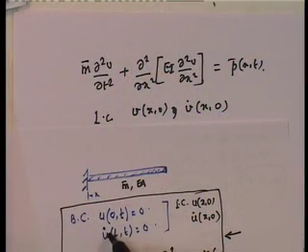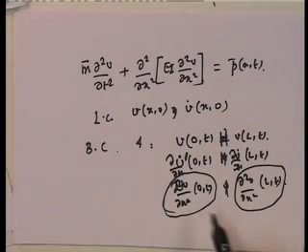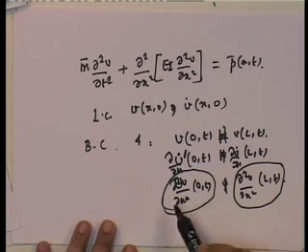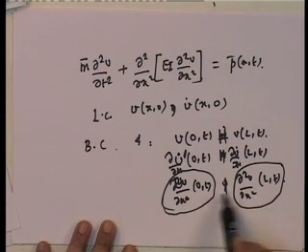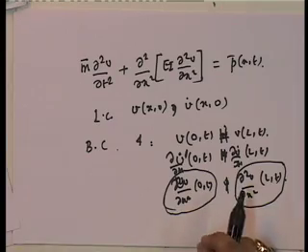Why is this? Because this is not strain, it is really the load, and there is no load here. So, the strain is equal to 0. Similarly, this is really moment, because curvature is related to moment divided by E I.